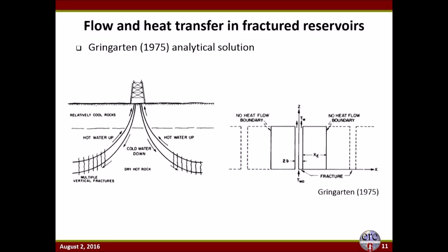The problem involves an injection well and a production well that are connected by several parallel fractures, and ultimately the goal of the problem is to understand how the water in the fractures heats up as it flows through the hot rock, and also how that's coupled with the heat conduction in the rocks surrounding the fractures.